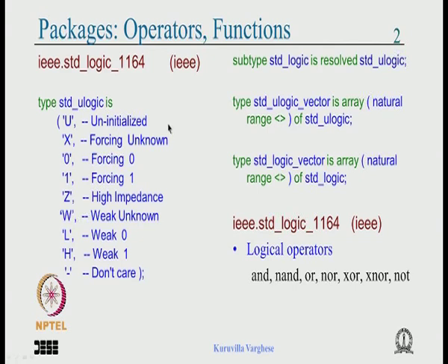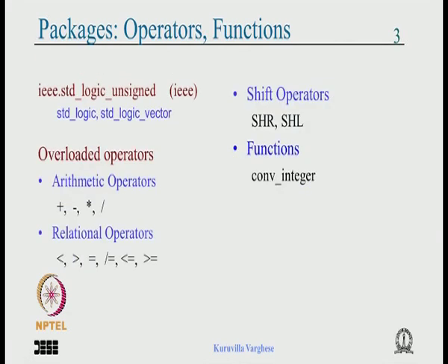It doesn't contain any arithmetic or relational operators. So if you use only the standard logic 1164 package, you will not be able to do much. You have to do very basic things, or you have to build everything of your own. But the moment you start using other packages, many other things will be available. So we have the next in line.